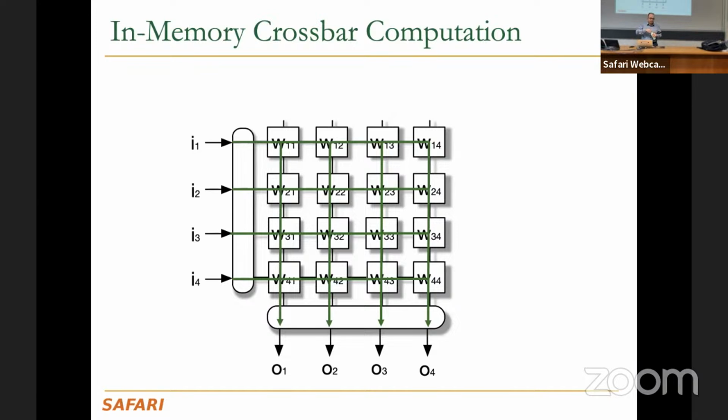Yes, you need to pay write energy and write latency to program an STT-MRAM, for example, or ReRAM. That's also part of the endurance issue. People have shown that using a ReRAM array is quite good for inference, where you program your weights one time and then do a lot of inference. But once you want to do training, where you need to update your weights, then your crossbar is going to wear out very quickly.